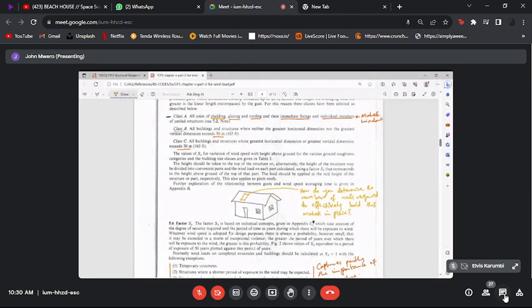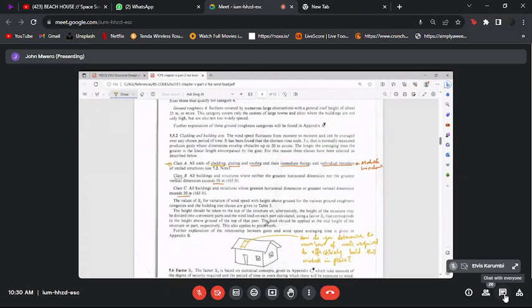Okay, so if you were to design, for example, a window that is resistant to this kind of winds, then the glass itself would need to be analyzed against the amount of force that it would experience. And for you to get that amount of force, the wind speed that you would need to calculate would be calculated against class A of the size of the building.